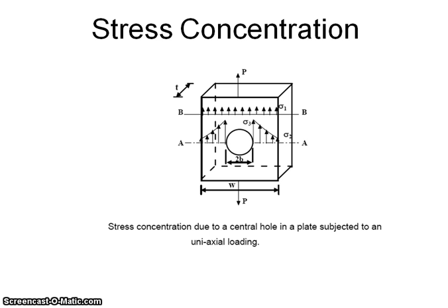If we use the elementary equations to determine the stresses, these equations do not give us the correct results. So we have to consider a stress concentration factor in the design in order to account for the maximum stresses developed near the vicinity of this hole.